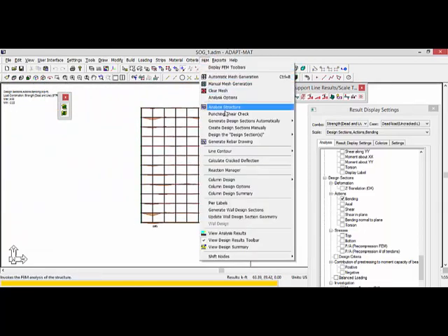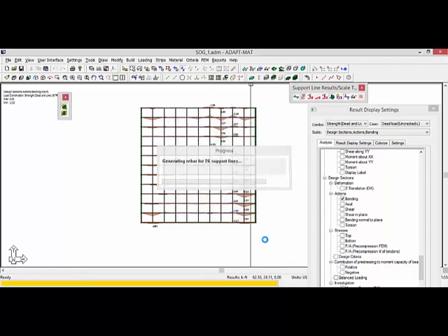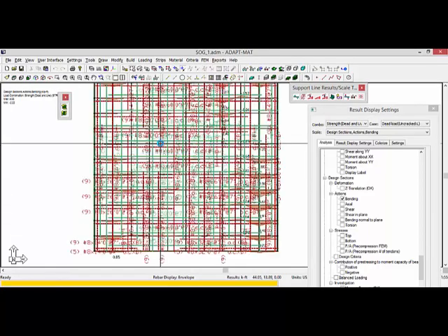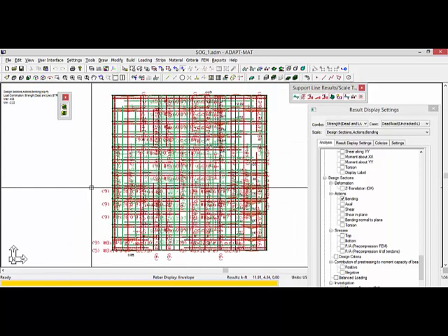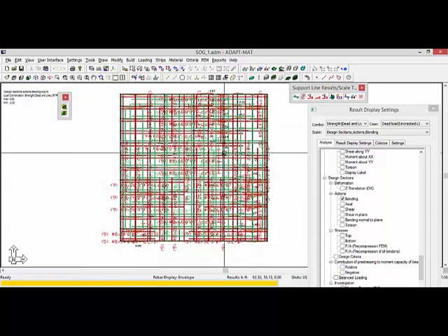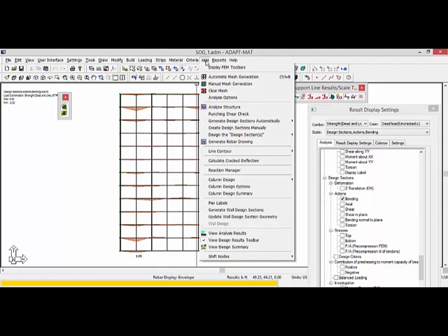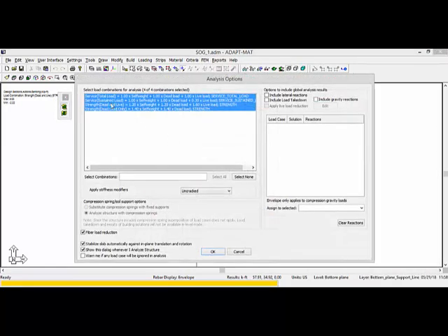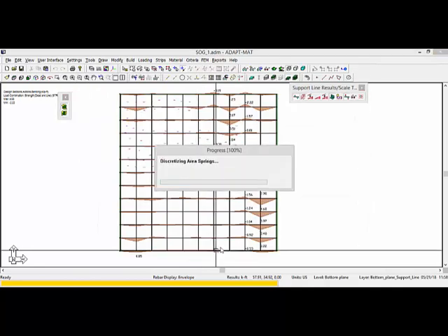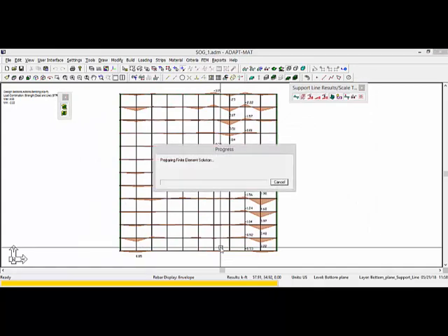And if we select FEM, generate the rebar drawing, under the enveloped condition, we can see additional bars that are required for this slab. Now, you can see there's quite a bit of reinforcement that's required, and one of the reasons that we're seeing this, so we'll go ahead and do that as an example. We'll go to FEM. I'm going to reanalyze the slab, and I'm just going to do this for strength dead and live and strength dead load only. I'll ignore the two minimum reinforcement cases. I'm still taking advantage of the nonlinearity here by this being selected, and we'll rerun the slab for this case.